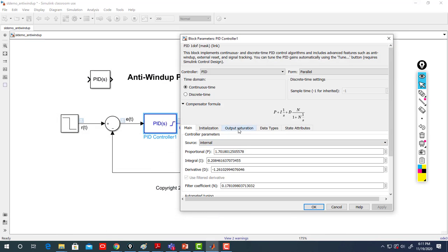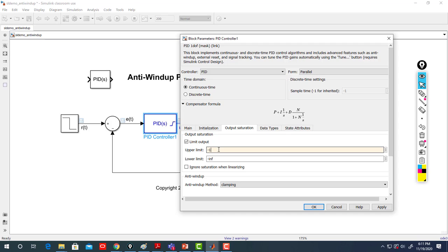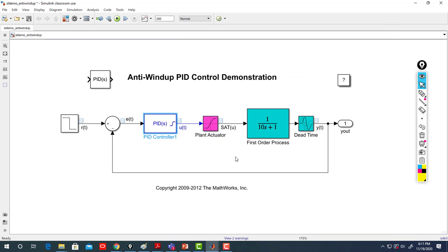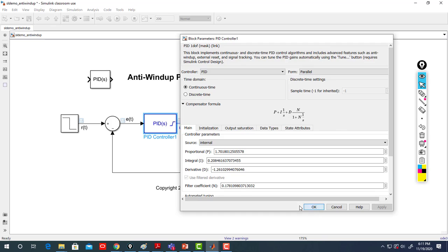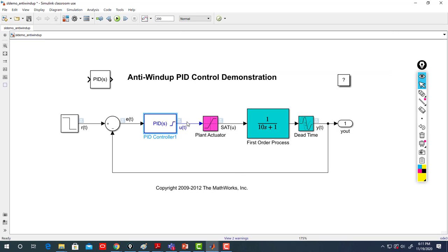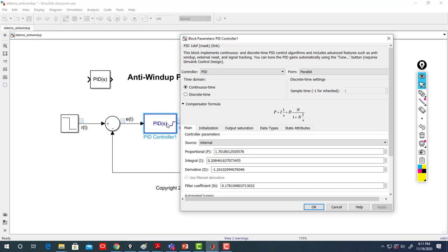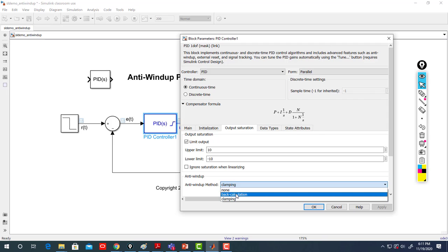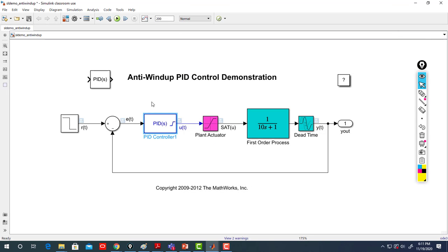And actually, if you don't clamp here, the inherent function inside MATLAB doesn't know that we need to have anti-windup, because it compares with infinity. So then this is something we need to do. No way. And we cannot access, unfortunately, the output in this case. Then, alright, no problem, we just stick to this value. It makes more sense. And let's see the remaining one, which is in this case the back calculation, and we keep it 1 for instance.